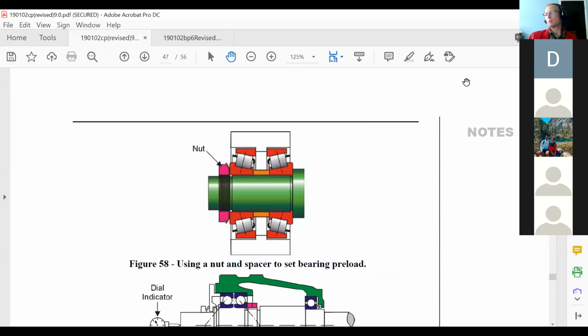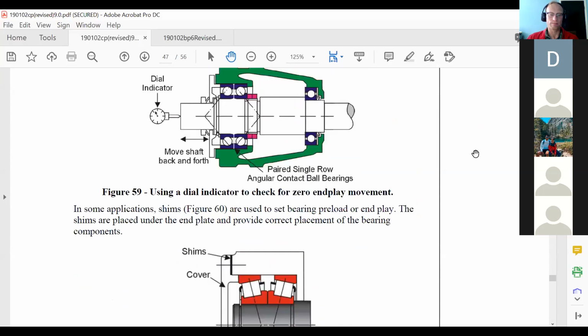So for us though, for trailer axles that we're going to actually be playing with, tractor drive axles and steer axles, in every case I've seen, and from all the literature from the manufacturers that I'm going to show you, you set your wheel ends to 1 to 5 thousandths end play, okay? And the last step we do before putting the hubcap on is going to be checking that end play, because it is very, very crucial.